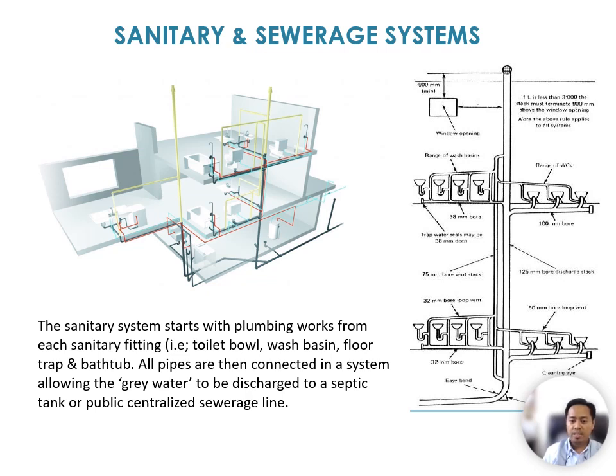On the other hand, we can see a vent stack. This stack will go all the way up to the roof. The function is to neutralize the air pressure inside the stack and allow for the grey water to move in a nice manner.